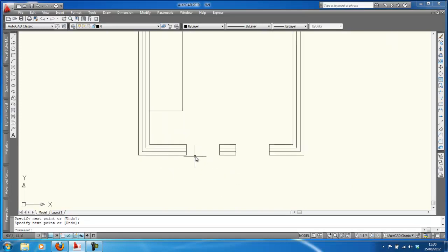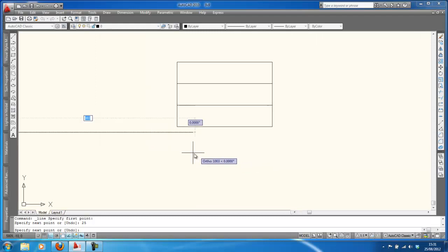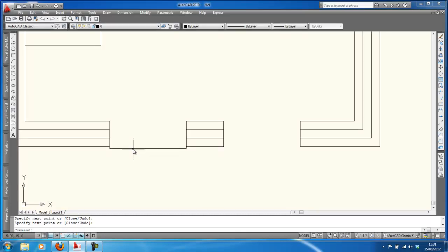With a door, even if it's a UPVC door, you will still have a threshold, and that threshold will extend a little bit beyond the front line of the brickwork, let's say 25 millimeters. Click. Can you see it's going to the side? Touch the corner to get your tracking, click, and snap onto the corner, and there you are. You have a threshold on here.